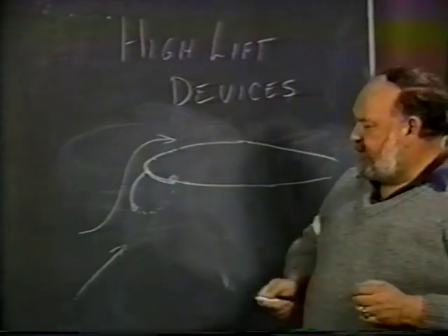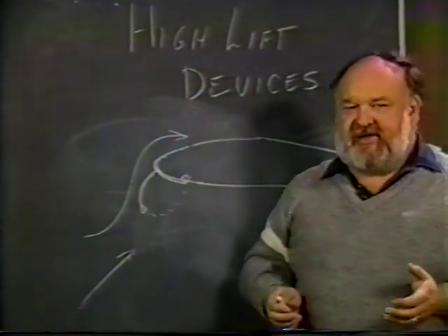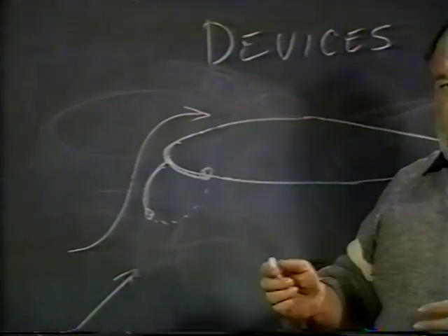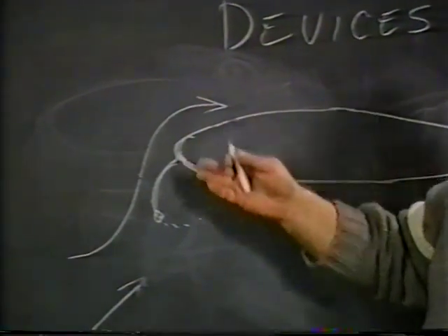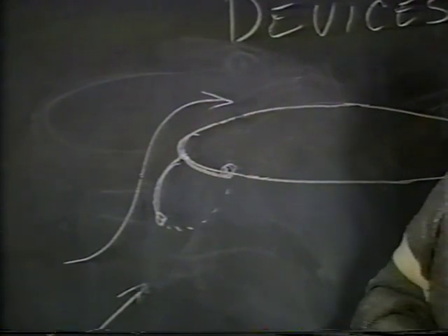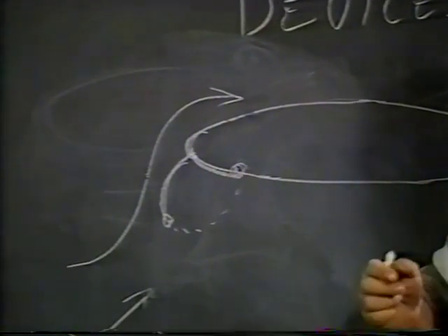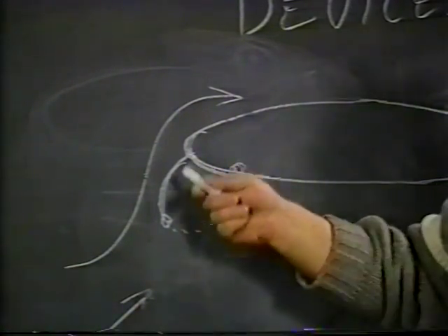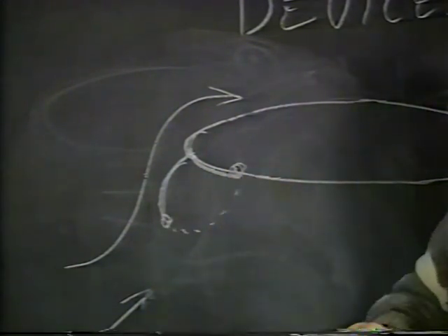You would not want to use a Krueger flap on an airfoil section that, say, is 12 or 14 or 15% thick, because really with any airfoil, your leading edge radius is already big enough. But when you're dealing with really high-speed airplanes where you must have a thin wing and you must have a relatively sharp leading edge, the Krueger flap can work reasonably effectively.